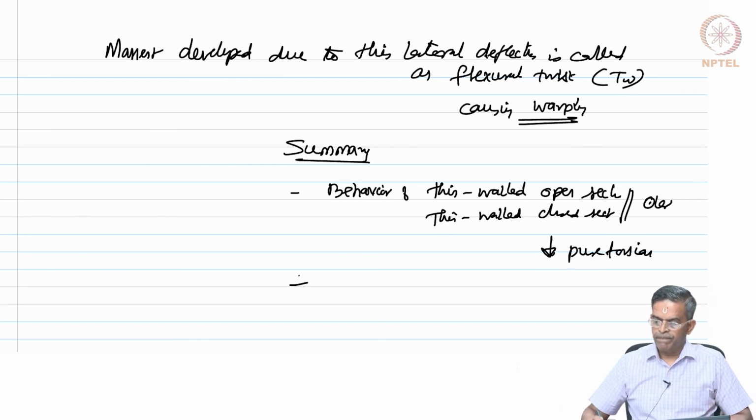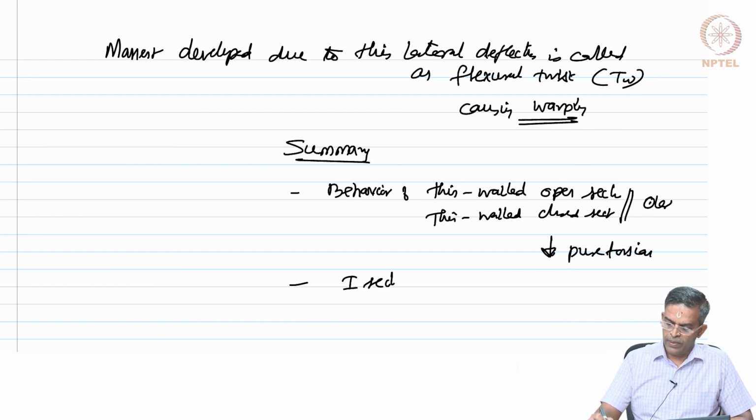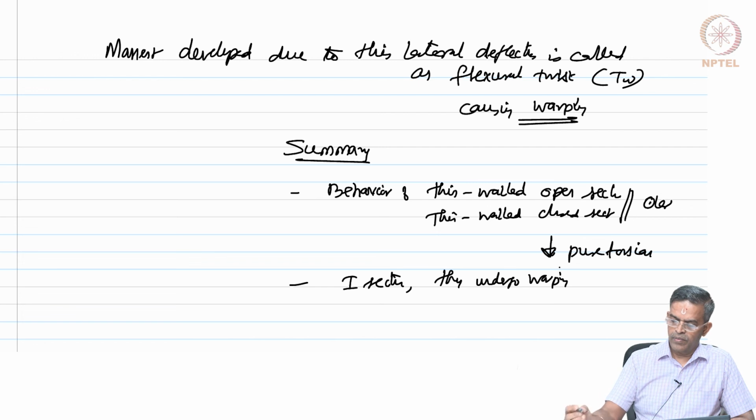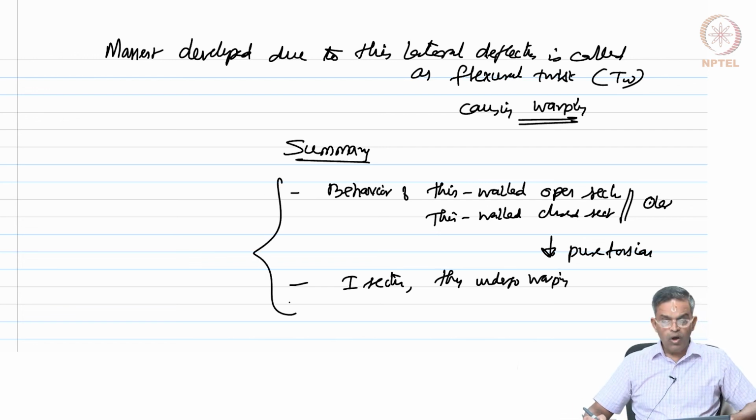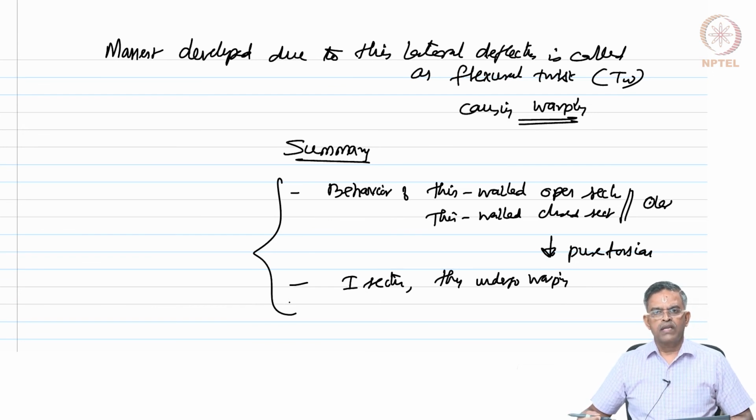On the other hand, open thin walled I sections, for example, undergo warping. Now our job is to find out the behavior of such sections under warping and try to develop a governing equation for the effect of torsion on such sections. We will discuss this in the next lecture. Thank you very much and have a good day. Bye.